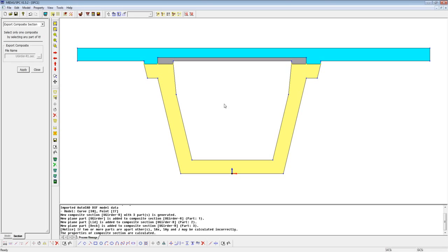And to consider the haunch, if you really want to consider its load and you want to be accurate in the dead load effects, then you can consider the weight of that haunch onto the structure as well. So in that manner, you can consider the variable cross-sectional properties due to the different haunch heights. There is hard to find a platform or a spreadsheet that will consider all those variations.